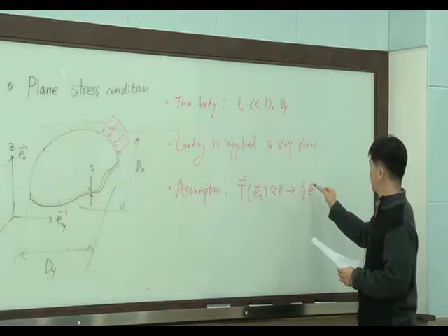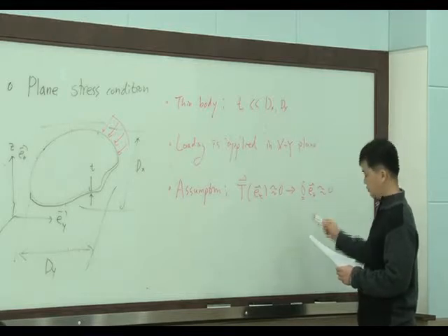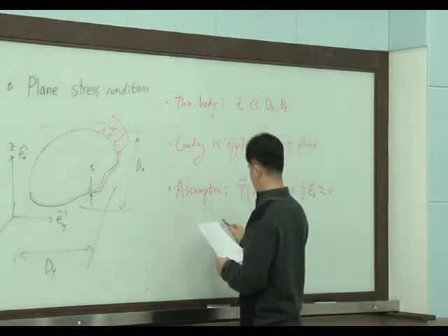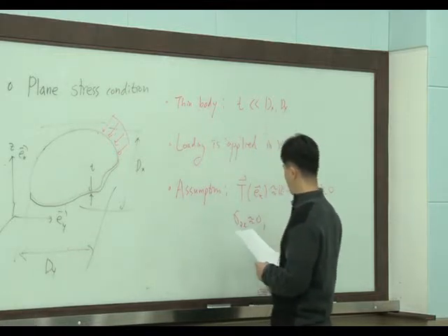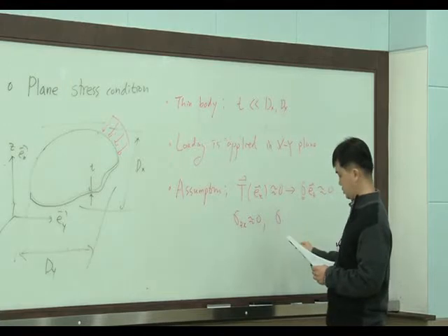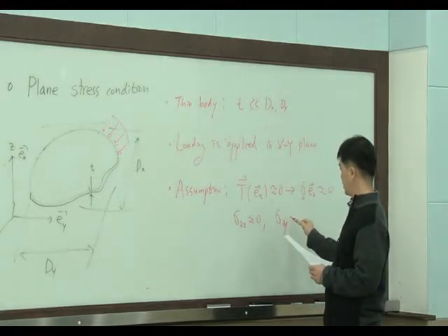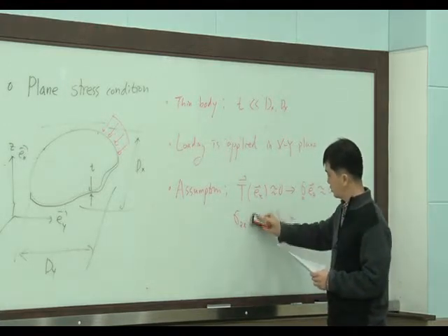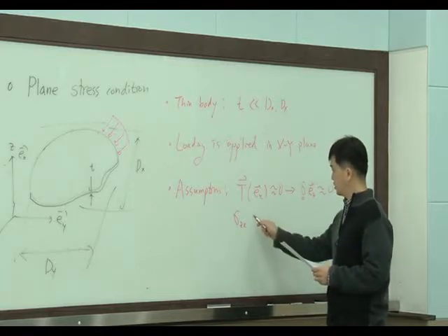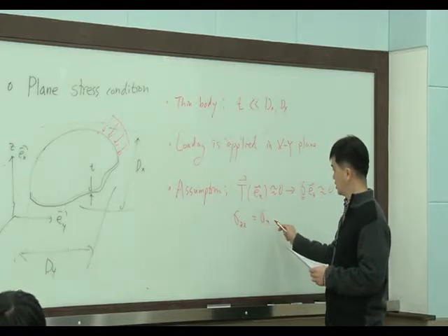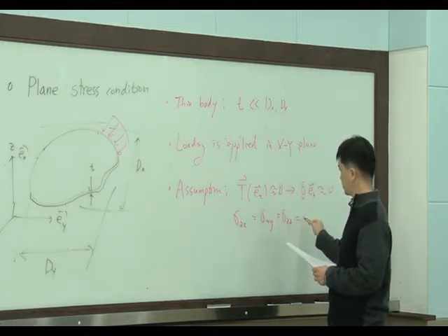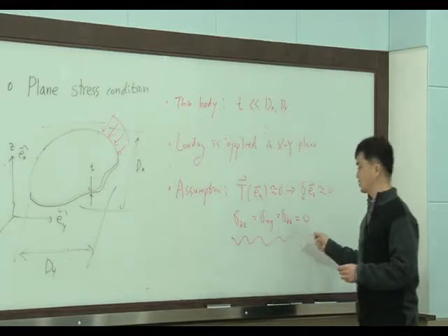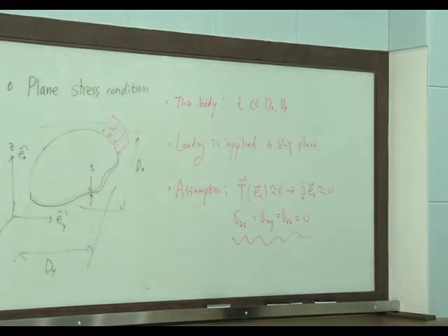It means stress sigma zx is almost 0, sigma zy is almost 0, and sigma zz equals 0. This is the assumption we call the plane stress condition.